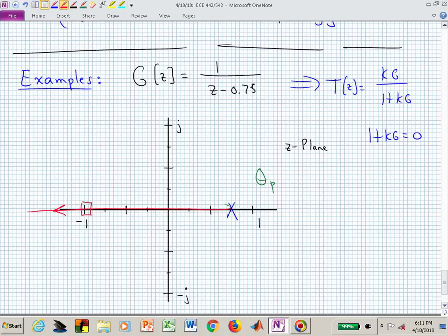What's the steady state error going to be for this proportionally controlled system? Will it be 0? Will you have zero steady state error due to a constant input in your closed loop system? You could derive it if you didn't see it, but you will not have zero steady state error due to a constant input. You'll have some error between where you want it to go and where it actually is, and that will depend on where you actually place that closed loop pole.